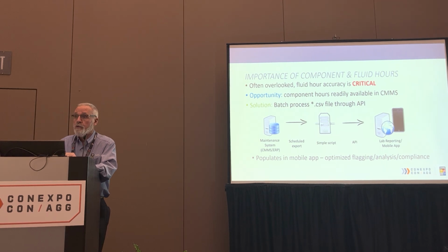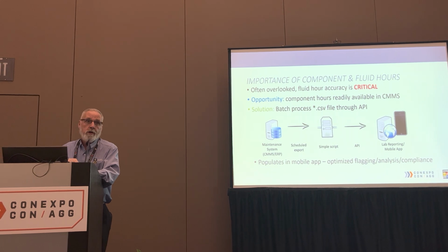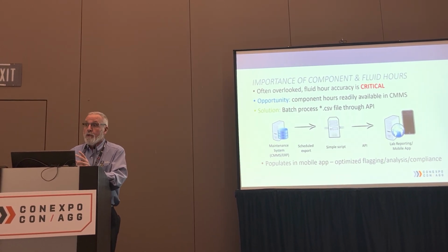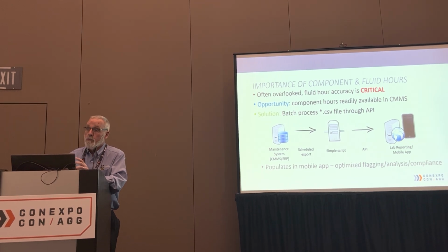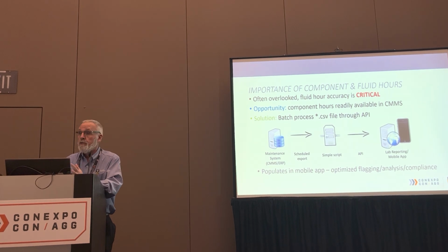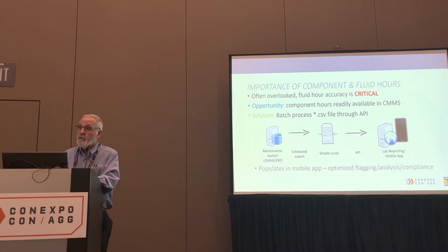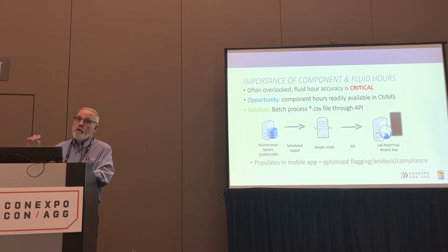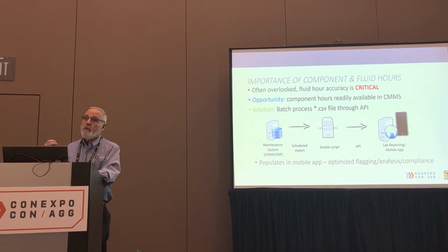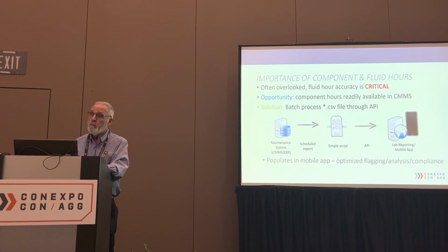a significant decrease in viscosity. That tells us, hey, it's not a problem with the lubricant. The lubricant isn't simply used up. You've got a real problem, a maintenance action that needs to be taken. In that example, maybe it's fuel dilution. You've got a bad injector. You're getting fuel dilution in the oil that's causing that viscosity to drop. So it makes a huge difference on the reliability of your fluid analysis results when the data analyst knows the component hours and the fluid time.